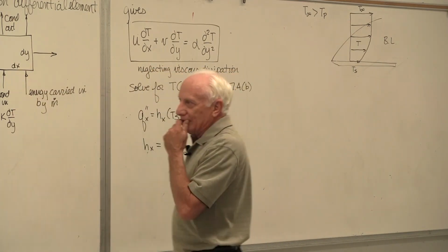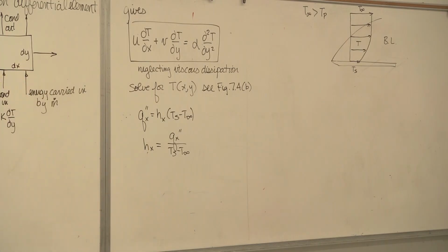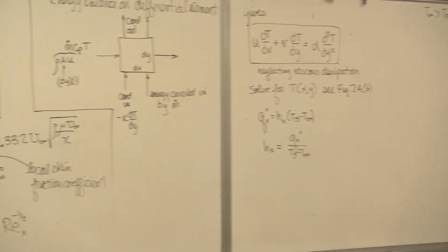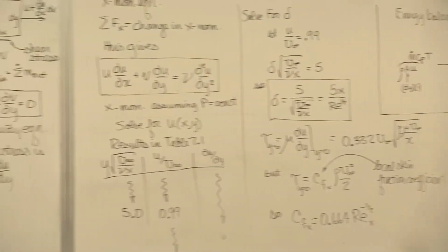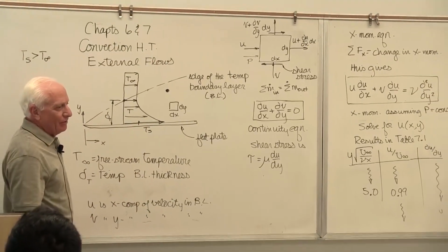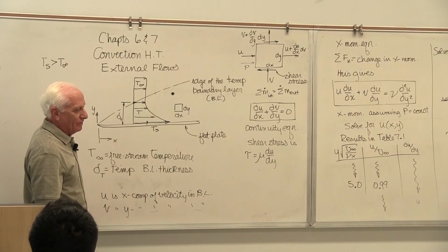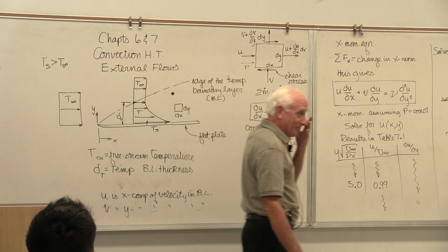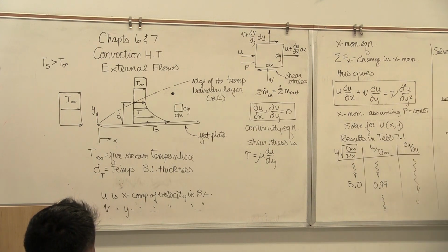Well, look at the picture. Let's see now. How does the heat get out of that plate? The plate's hot. The fluid is colder. It leaves the plate right here where y equals 0. And here comes the catcher now. You tell me the velocity of the fluid at the plate surface, and I'll give you the answer. It's 0, the no-slip condition. The no-slip condition, ME311. That means the fluid is not flowing at y equals 0.